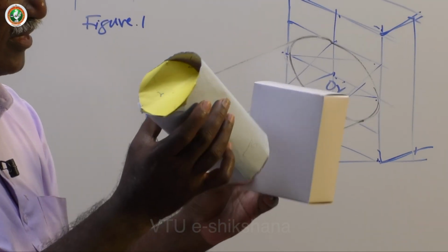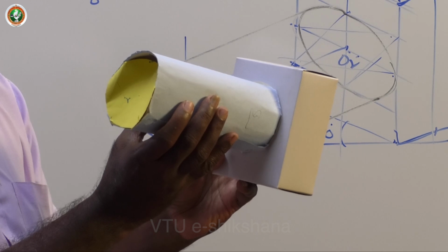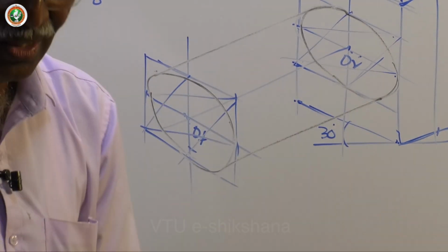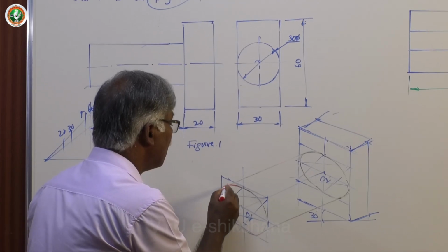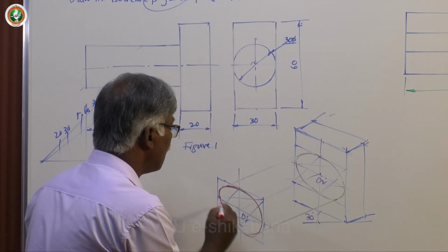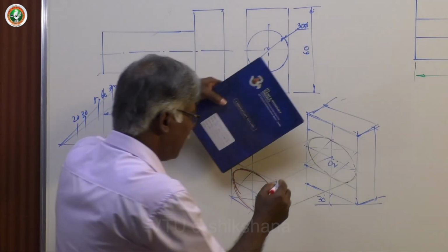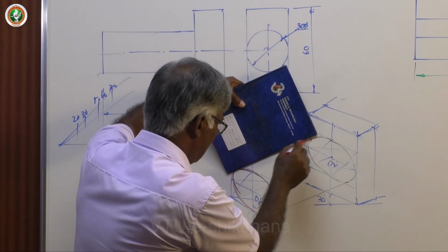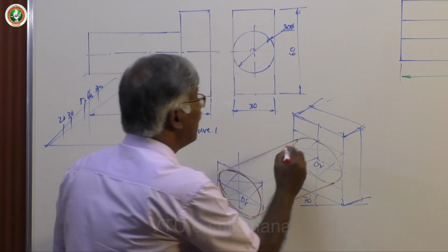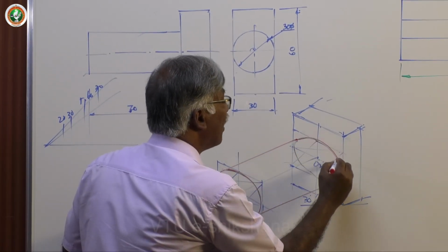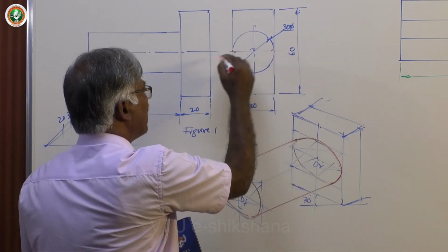Then the surface, as usual, is visible, but it's covered by this front solid, or part of the solid is not visible. So first let me complete the visible surfaces. This is visible. Draw a smooth curve. Then these tangents must be available and visible. 30 degree line only. Then the boundary is completely available. See that it is touching it because these 2 points are key points.